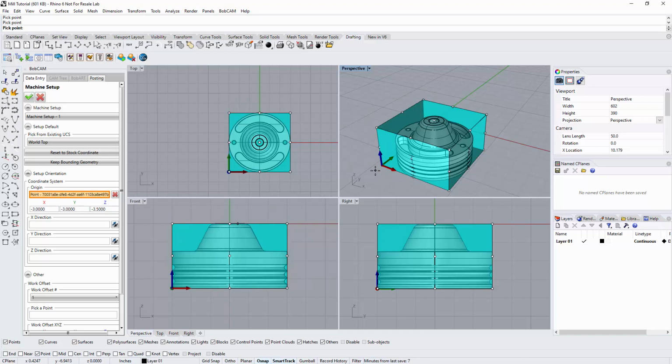Some routers, you may not have to do this, but some routers, you might be going off the spoil board. So you have to remember that the top of feature would now be 3.5 inches tall. And so when we start tool pathing, we need to make sure that our origin is referenced properly. Basically, what we're choosing right now is the location that is shared between this selection that we're picking now and the selection that we're going to have at the machine.